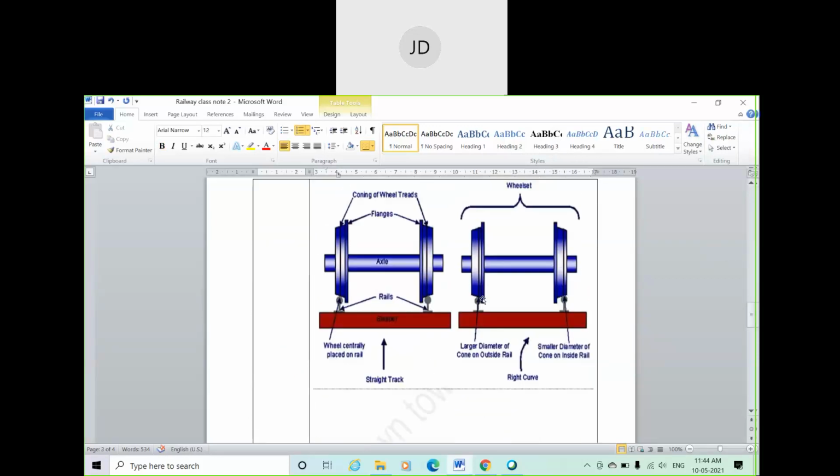Here, I'm talking about here. You can see when the train is taking a right turn, the gap between the flank and the point of contact between rail and the wheel is very close. That means there is a chance of friction, and because of the friction, there is a chance of failure or crack in the flank. In other words, there is a possibility of wear and tear of the wheel flank, even along with the rail part, because of the contact.